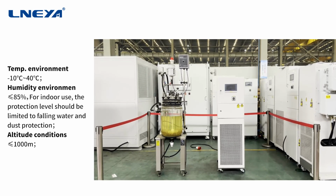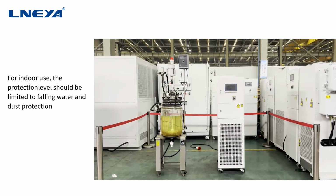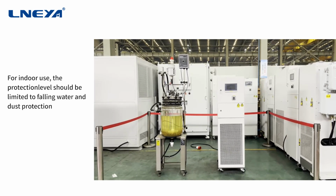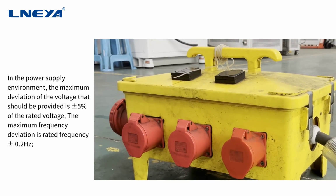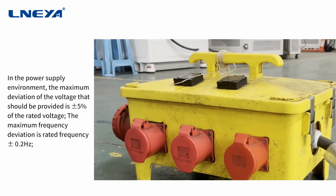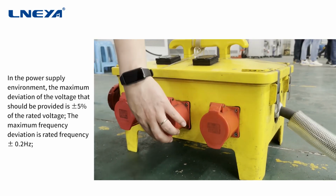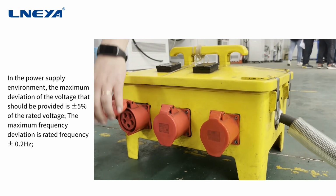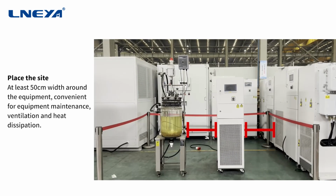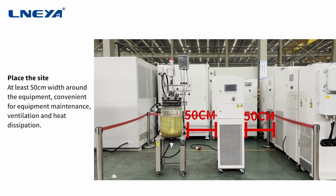Altitude conditions: less than or equal to 1 kilometer. For indoor use, the protection level should be limited to falling water and dust protection. In the power supply environment, the maximum deviation of the voltage that should be provided is plus or minus 5% of the rated voltage. The maximum frequency deviation is rated frequency plus or minus 0.2 Hz. Place the site at least 50 cm width around the equipment, convenient for equipment maintenance, ventilation, and heat dissipation.